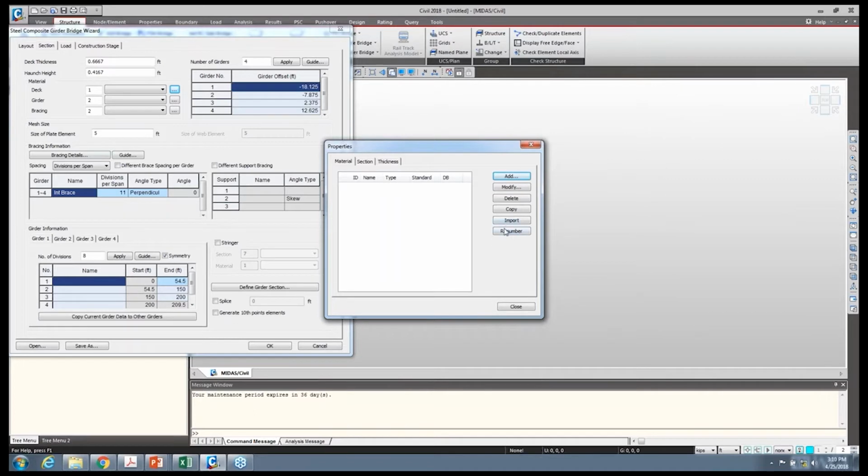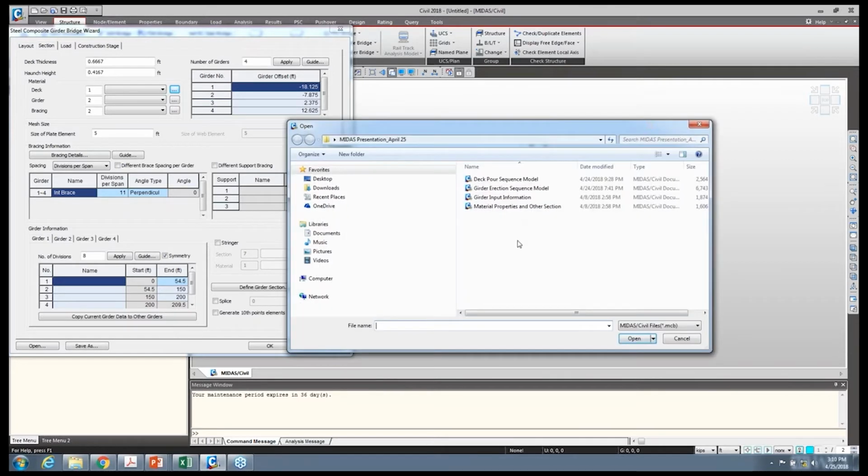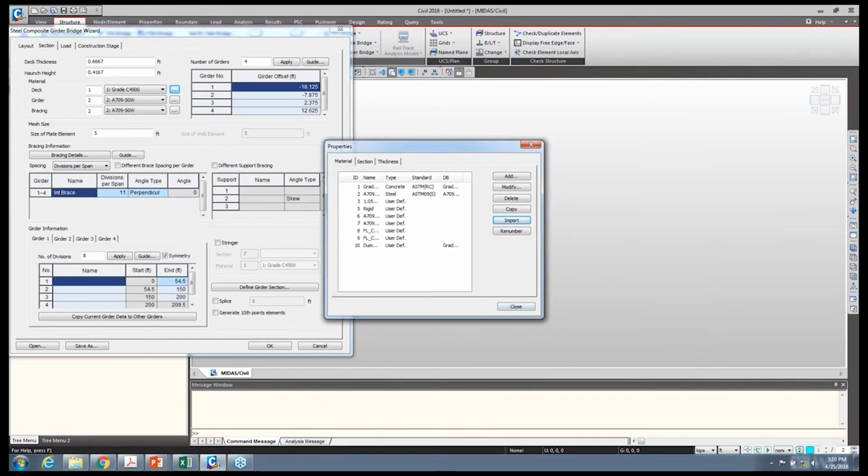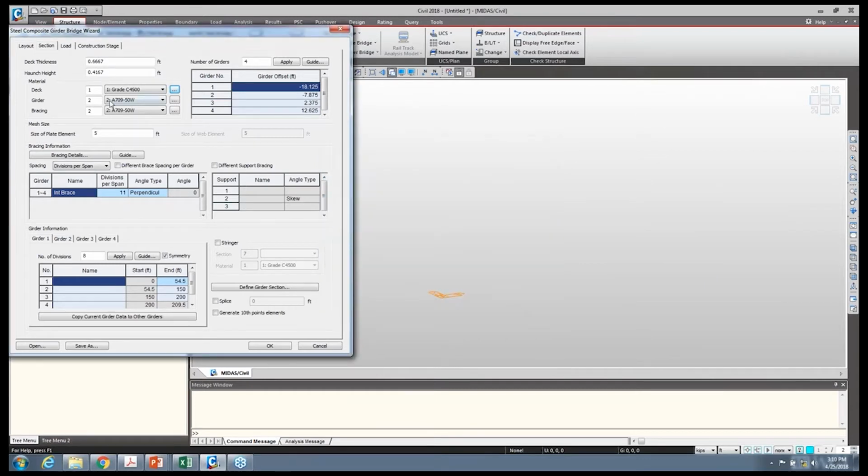For the bearing type, you have two options: bearing type or with substructure. Because the wizard file does not create a straddle pier, I'm not going to select the with substructure feature. Instead, I'm just going to select the bearing type, and I plan to remove the interior supports created at Pier 1. So I'm going to set Pier 1 as my fixed support, but we're going to go ahead and adjust that later as we begin to modify the model. And finally, the direction of the support. Please use this for your own particular design needs. Once again, I'll be modifying this later in the file.